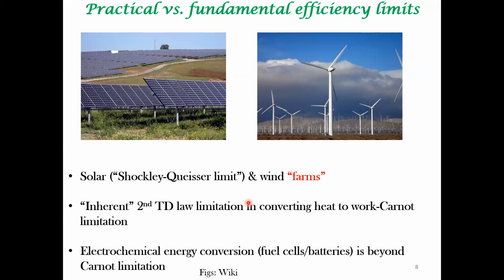And there are high temperature fuel cells, the solid oxide fuel cell. The input is hydrogen and oxygen, and the output is H2O, so there's no pollution. They operate at very high temperature, and if the high temperature water vapor that is generated is combined with a turbine, the efficiency is more than 90%. This is remarkable. If you look at the efficiency of a thermal power plant, it is about, let's say, 40%.